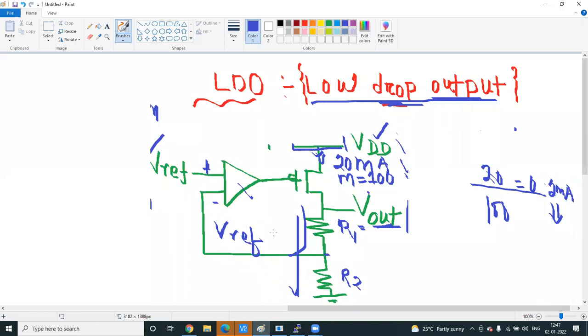Now we are considering EM also for the op-amp case. If you see this current is going, but this current is not dividing to the op-amp. The gate will not carry any current, and here also no current. So the op-amp current will be very less. That's why we are not bothering about EM. Sumit, you understand?